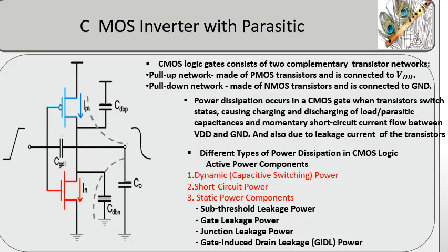The output resistance of the inverter along with the output capacitance determine the output rise and fall times, while the source driving resistance and the effective input capacitance determine the input transition time. The combined charging and discharging delays from the input pin to the output pin define the propagation delay of the CMOS gate, making parasitic capacitances the primary contributors to gate timing, switching speed, dynamic power dissipation, and ultimately the performance of the chip.